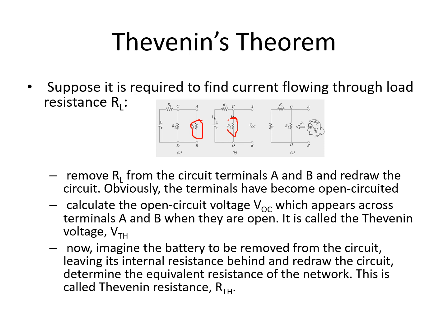If we want to solve for VTH here, we just use the voltage divider principle, since the voltage E will divide between these three resistors: the internal resistor r, R1, and R2. But what we are looking for is the voltage across R2, because whatever the voltage across R2 is, it is in parallel with our open circuit here, therefore they are just equal.